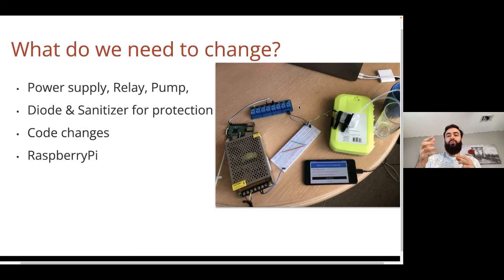And so you'll hear it click. And so it'll let the current pass through to the pump. This over here is a pump. There are different types of pumps. This is a peristaltic pump. You can use any one. But the thing with the peristaltic pump is that it has a lower flow rate, so you're not flooding everything. And also, it does not contaminate whatever's inside it because the pipe just runs continuously. And so you can use a food grade pipe that's very safe to use. So it's not going to contaminate the food or oil or whatever drink you might have. So pretty safe to use.